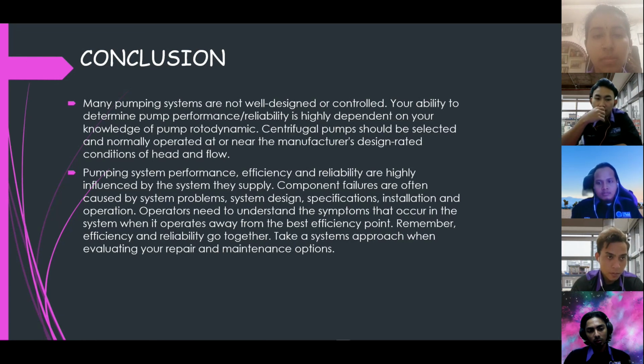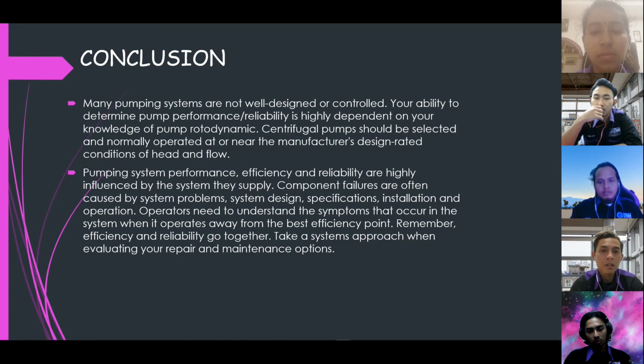The pumping system performance, efficiency, and reliability are highly influenced by the system they supply. Component failures are often caused by system problems, system design, specification, installation, and operation. Operators need to understand the symptoms that occur in the system when it operates away from the best efficiency point.